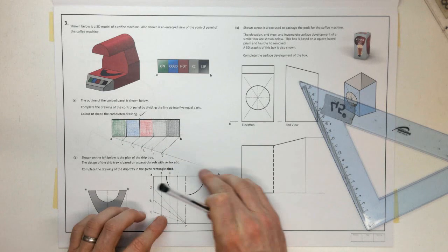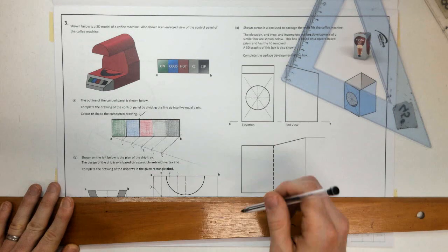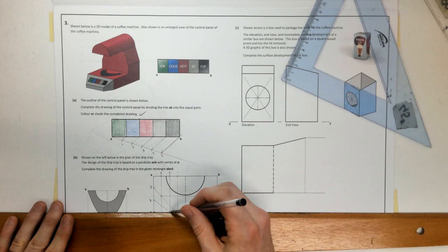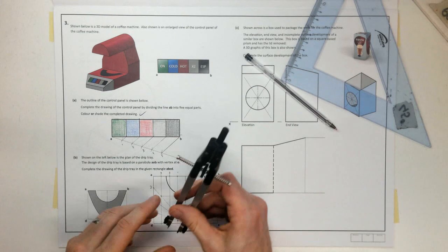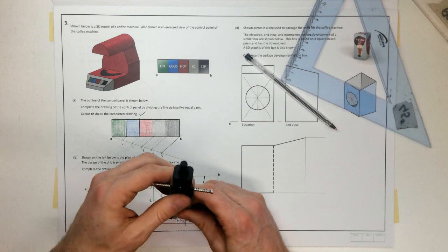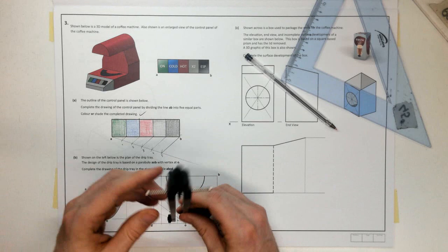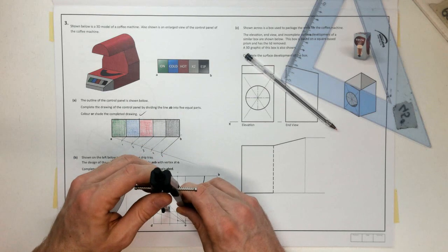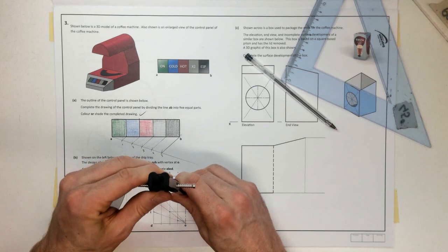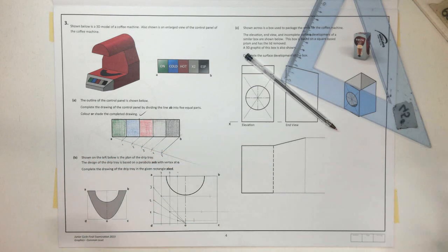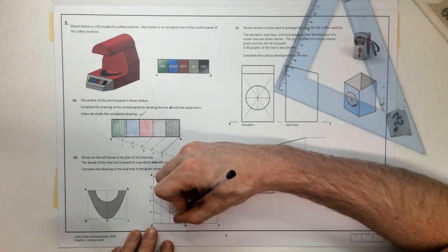I could repeat all that same construction on this side, but just to show off a little bit, I'm going to do axial symmetry. Your call, you'll get the marks regardless. So point of my compass on the axis, set it to the distance to that first point, and swing an arc. Same here, set it to point 2, swing an arc. And then finally to point 3, swing an arc. So we've got all our points there, and we can draw our freehand curve.